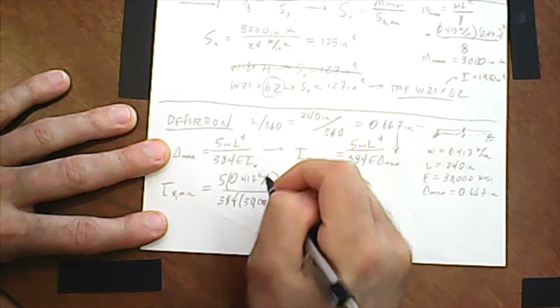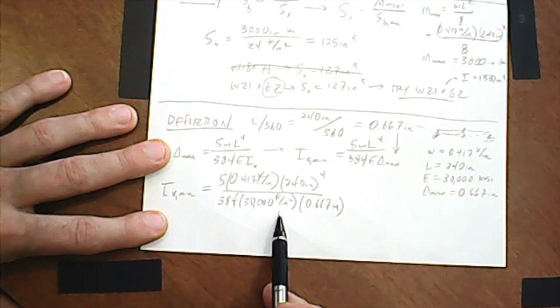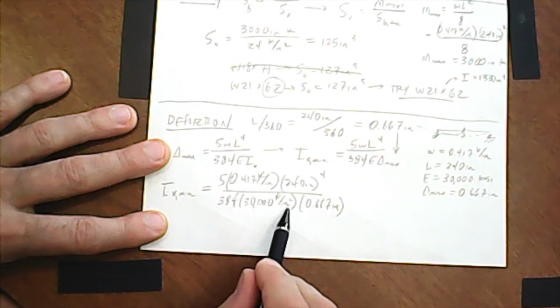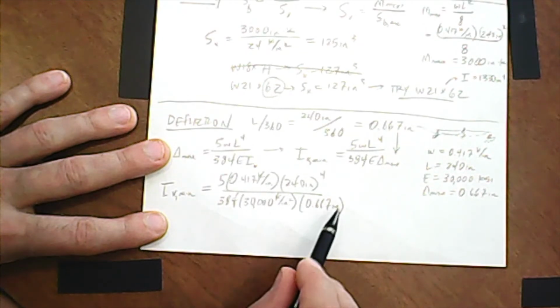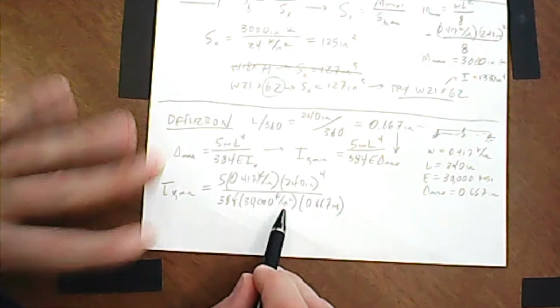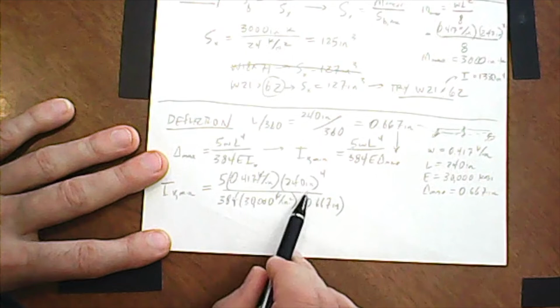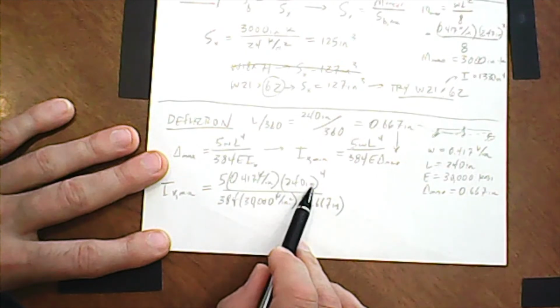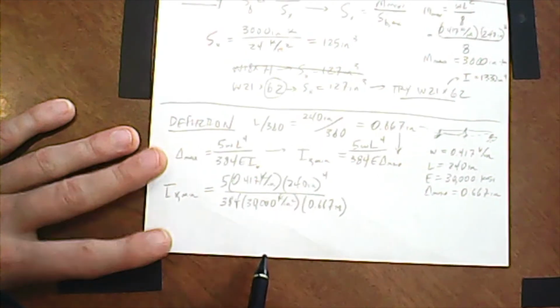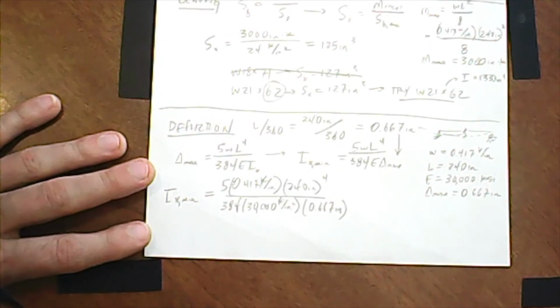Well, let's see, the kips cancel. That's nice. So we just have a bunch of inches here, don't we? So it looks like we have inches cubed on the bottom and inches. So we end up with inches divided by inches squared. So that would be 1 over inch, and that jumps up to the top. And we have kips per inch times inches to the 4th. So we end up with inches cubed plus that inch jumps up to the top. So we end up with inches to the 4th. So that's good. Always a nice exercise to do.